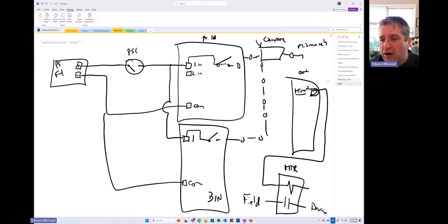If those 2 values are mismatched, I need to de-energize the mismatch output to a separate relay that's going to allow me to de-energize all my power to the field. So this is what needs to be done for every input to address the potential of a stuck input.